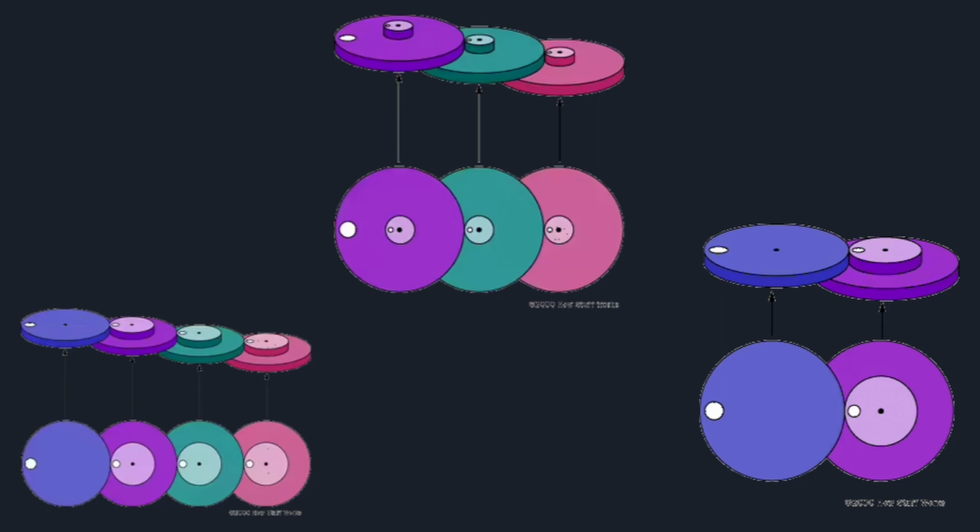And this can work even better when you have other gear mechanisms like worm gears, which can transfer the axis of rotation. Therefore, you can compact it, kind of fold the rotation on top of itself. And what that does is it prevents it from taking up too much space, which on a robot is very useful. Although realistically, you're not going to be needing that much torque or speed in an FTC bot, but it is there if you need it. So there's that, and I think that should be it for this video, guys.